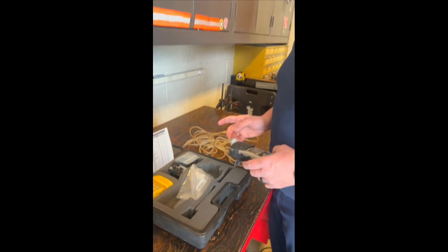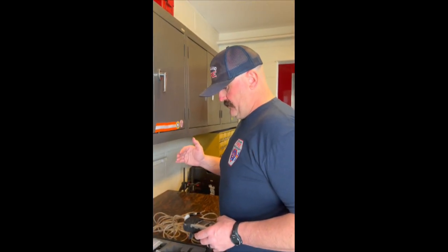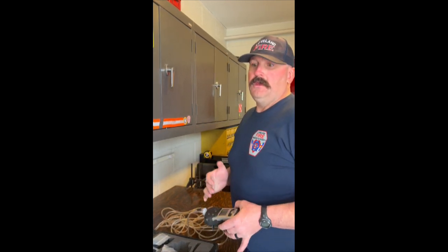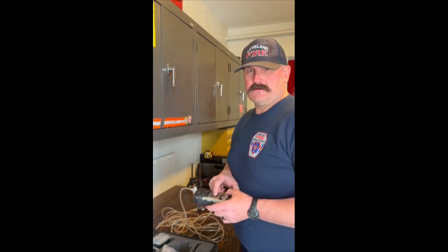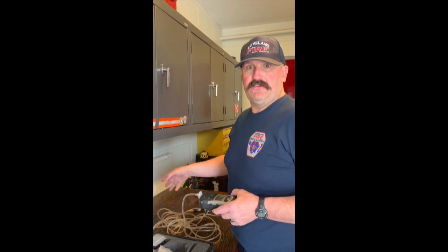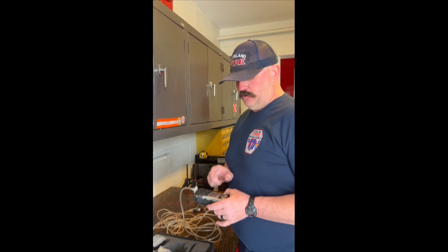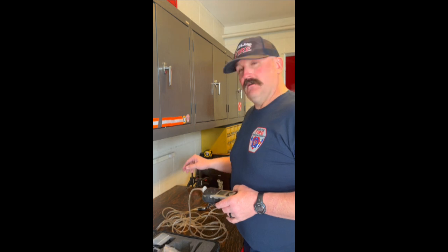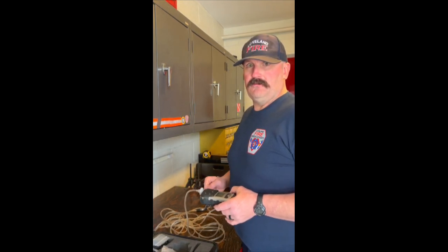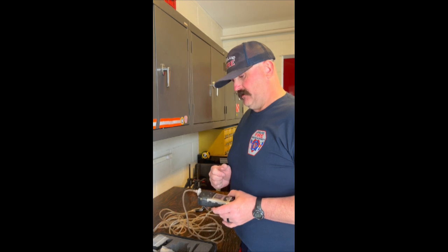It's important to remember that because you're not monitoring the direct atmosphere you're in, you have to give it some time to get through the tubing. General rule of thumb is about 2 seconds for each foot of tubing. So for 20 foot of tubing, 40 seconds or so is the time that what we're seeing on the monitor is what the environment was at the end of the tube 40 seconds ago, right? That shouldn't change within a minute. It's just important to know that if we turn this on right away and attach tubing, what we see here is not accurate of what is coming into the end of the tube, right? It's after about 40 seconds that we'll get that accurate reading.